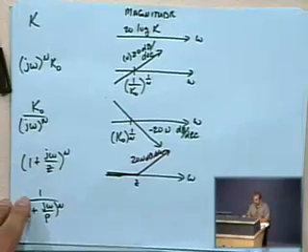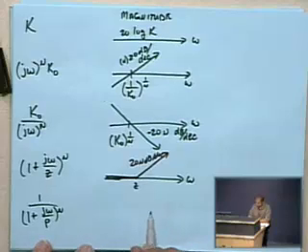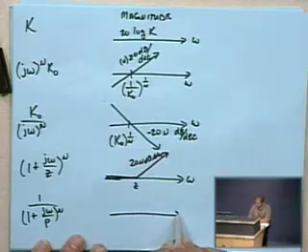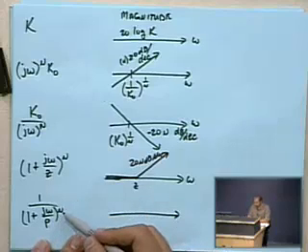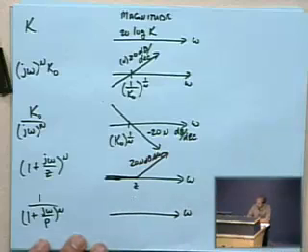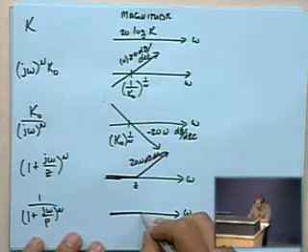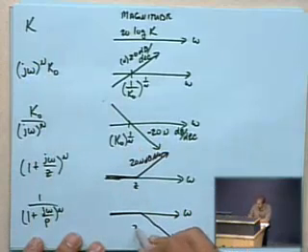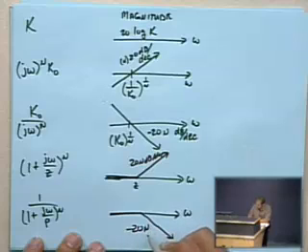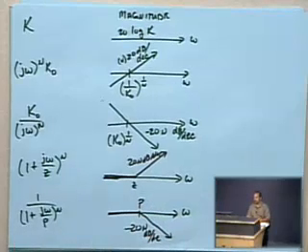And similarly, simple pole terms of any degree will head along the axis for some period of time, and then will decrease at negative 20 times n dB per decade. That change will occur at the frequency p.